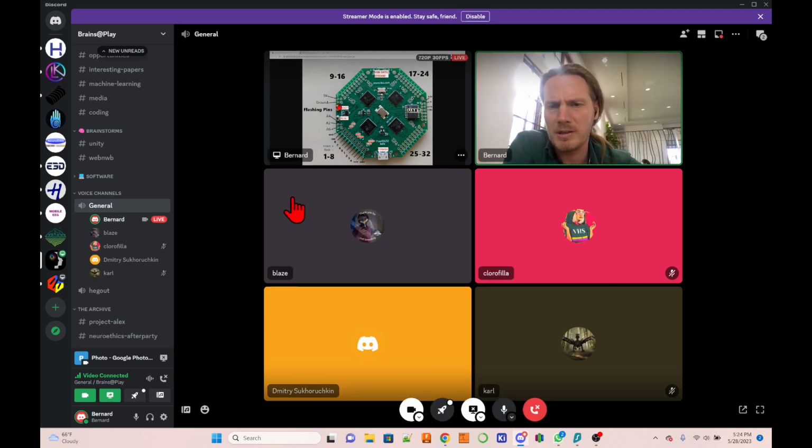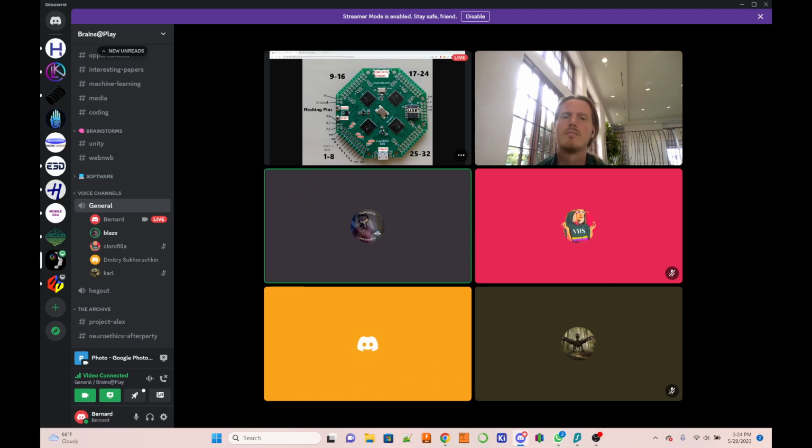But I would not recommend using this. We only use this when we flash the board, because when we flash the board, we have to power the system, and then we do it using these pins, and not the USB port. But then that's an input, is it? I thought you were saying that that's shared with the DC-DC transformer. So that 5 volt is an input for flashing. Yeah, but we don't use it while we're measuring EEG.